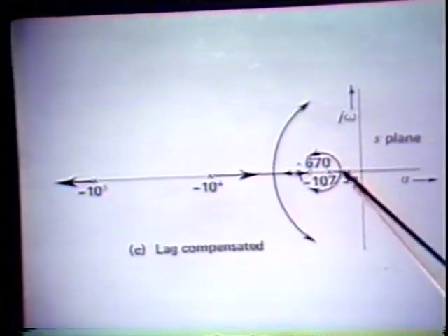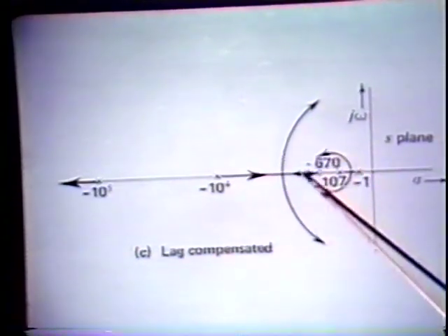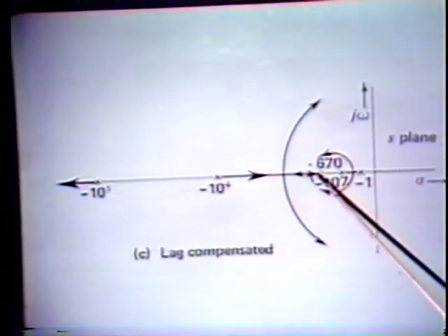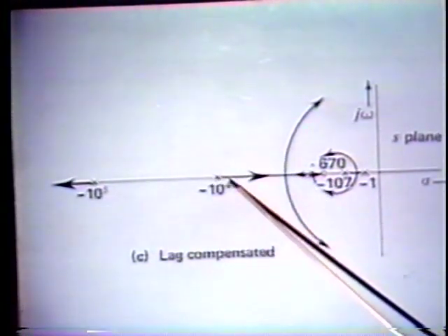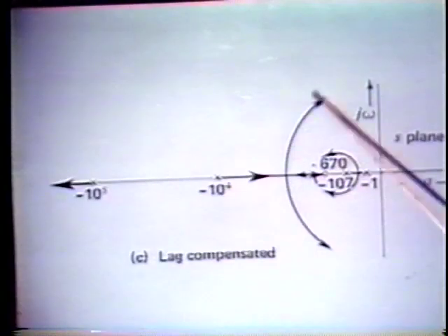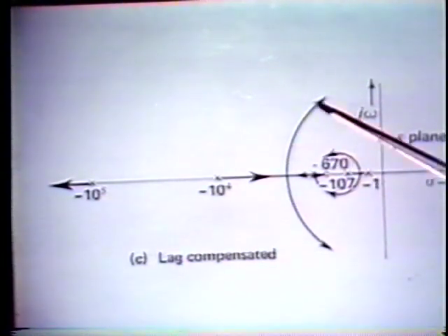We do the root locus diagram. These two branches come together, circle around. One branch heads toward this zero. One out here, which joins this branch. They then spread off. And the pattern out in here looks very, very much like the uncompensated case.